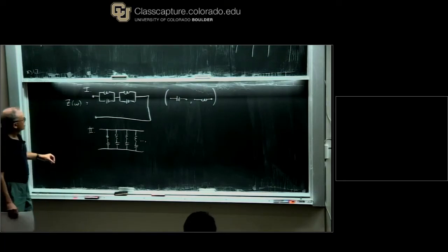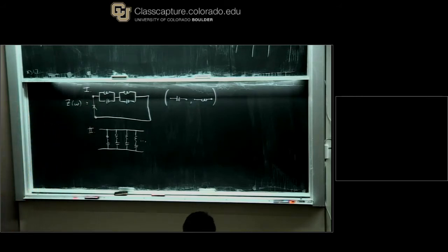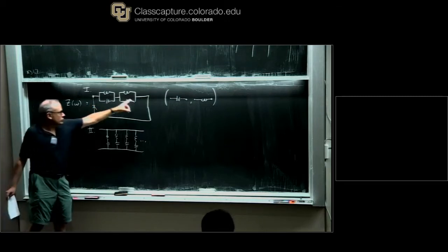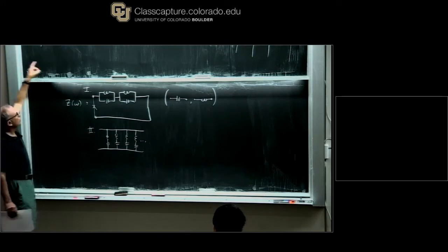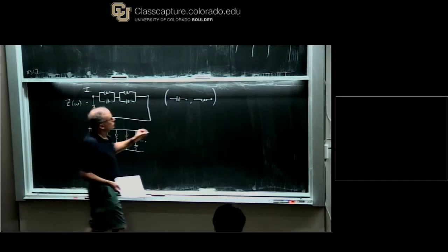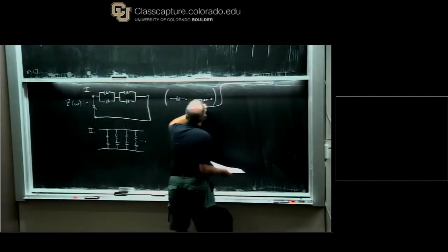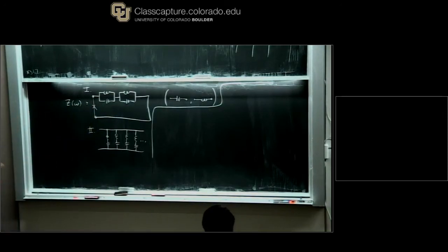All right, so we're kind of close. That is, we'd say, well, our actual circuit is this. That's still not quite what I want to do, although that could be the story. That is, it says, good, that's the electric circuit of the Josephson junction with the transmon capacitor around it, and then with all the other stuff around it. That turns out not to be the most informative use of this Foster 1-2. And so to describe what we consider a good or best representation of this circuit, a minimal approximate representation, it's best to actually mix these two.